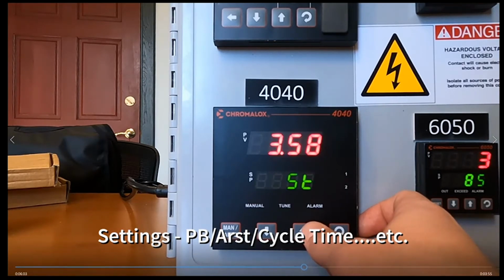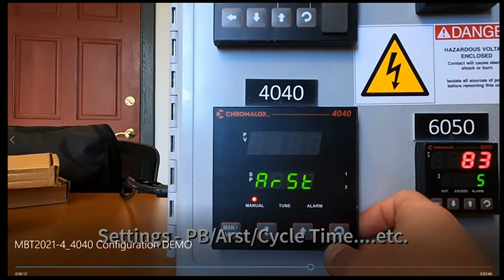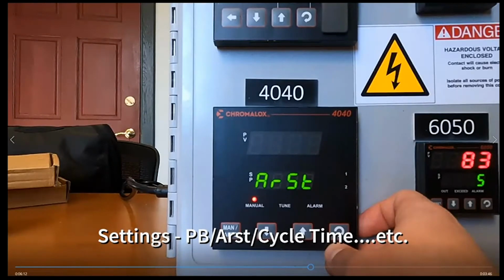Derek, do you want to? I like the way that you described the reset time there, if you want to speak to that briefly. Well, yeah, the auto reset. More often than not, when somebody's controller isn't operating properly, I immediately go to the auto reset, because the controller is trying to interpret the information that's coming in. This is the window that the controller is interpreting from. So if it's a fast acting process, like a flow or something, where the variables change quickly,